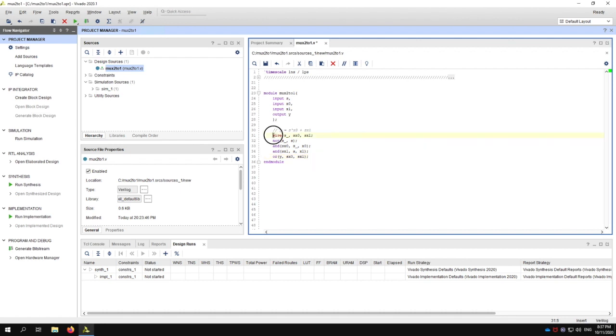So the first thing that I did was I declared all my wires, all my internal wires that I needed. This is similar to on a breadboard, if I took a red wire and made the red wire the output of my inverter, where the input was my signal S. And I had, let's say, a blue wire, which would be the output of an AND gate that had S and X0 as inputs, and similarly a third wire called SX1 that was the output of my second AND gate.